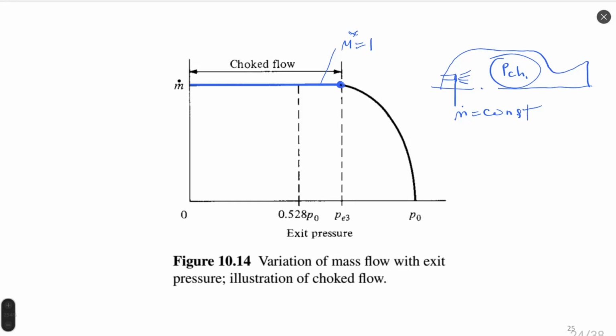This is very useful because you can separate the flow in the injector from conditions of flow inside the combustion chamber. So you can independently control these 2 parameters, and this gives us a lot of advantages in organizing efficient propulsion.